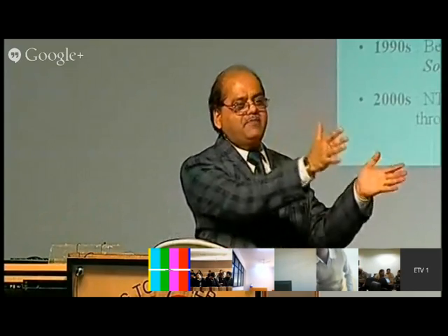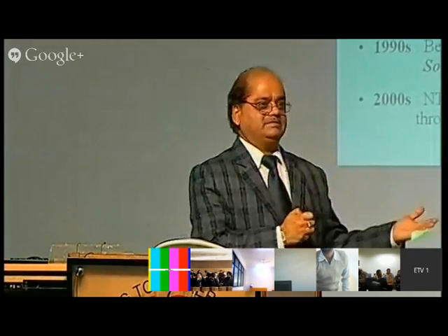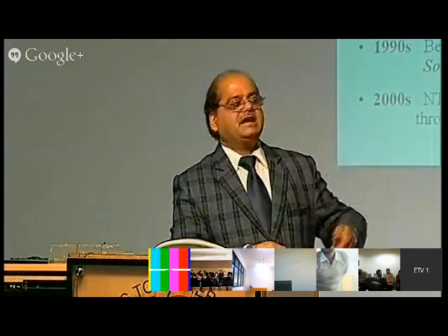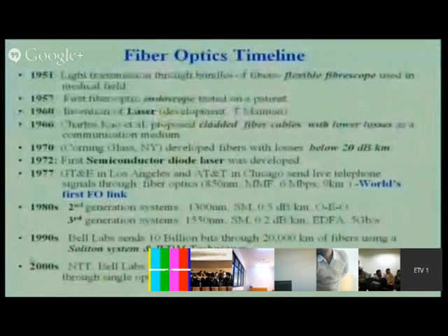I can send a number of wavelengths over the same fiber, provided they are different wavelengths, because different wavelengths travel different distances. So with WDM technology, and then in 2000, the 21st century, companies are working to send trillions of bits per second, terabits of data, through a single optical fiber, and that led to the development of all optical networks. So we now need all the optical components.